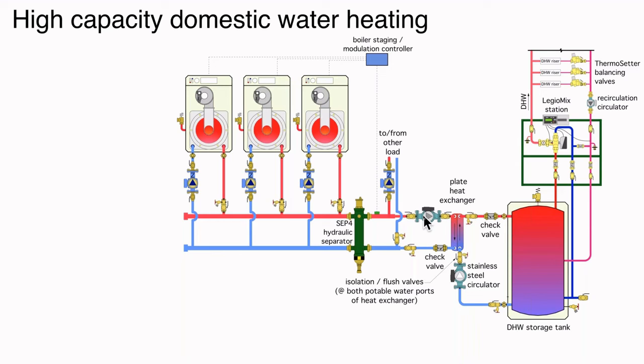So make sure as you size these circulators that you're sizing them for the flow rates that you need to affect the rate of heat transfer. And the idea is that you should be able to take every last BTU per hour that this array can produce and put it into that tank under reasonable temperatures and flow rate conditions. So that, again, we'd go back to the sizing software and do our what-ifs: what size heat exchanger do we use in a system like that.